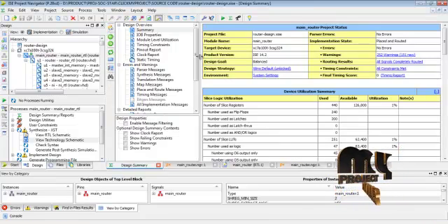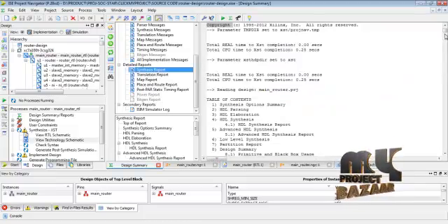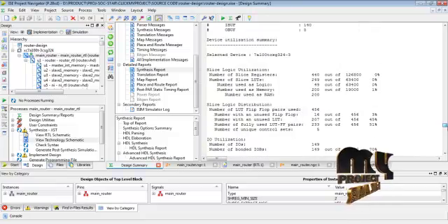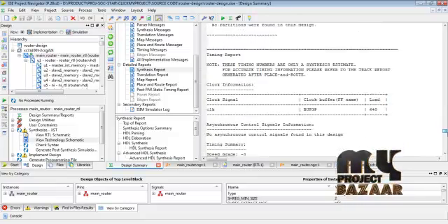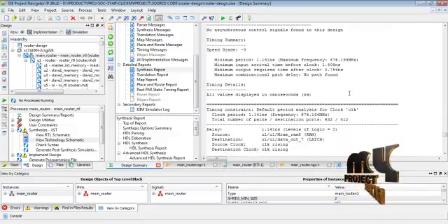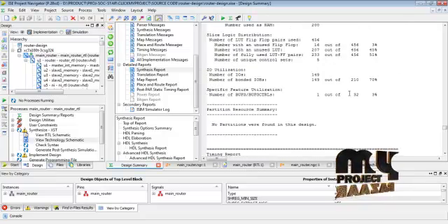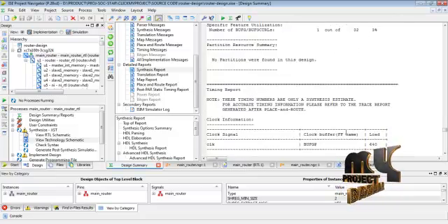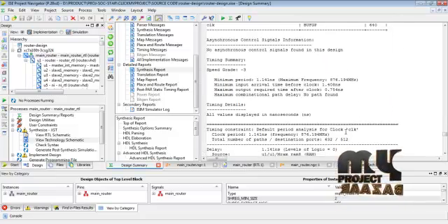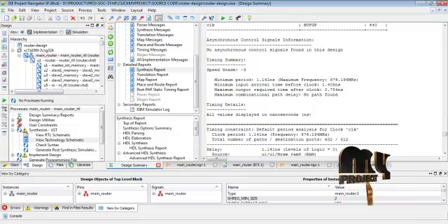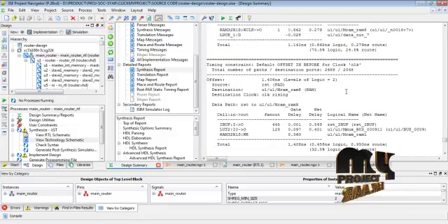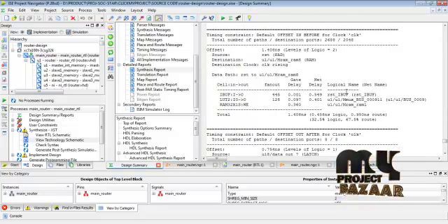Then go to the design summary process. The design summary process produces the final synthesis report for our architecture designs, for device utilization, and calculates the timing summary results. The device utilization mainly represents the lookup tables and flip-flop pairs, then the bonded input output functions. The Xilinx design timing summary results represent the minimum period time and clocking frequency level, then the before and after clock function for the overall architecture design. These are the final output results for our forecast NOC architecture designs.